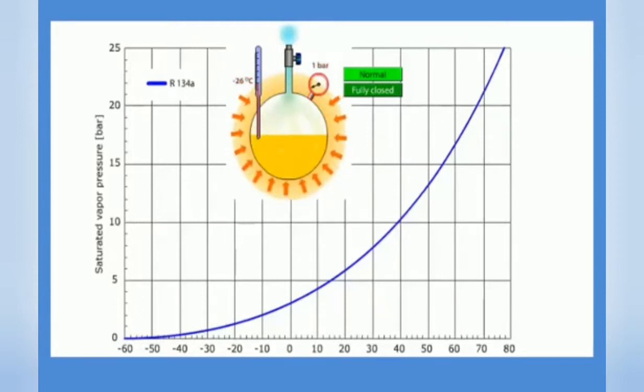When a single refrigerant is confined in the flask, it will exist in a thermal equilibrium as a mixture of liquid and vapor. The pressure in the vessel is solely depending on the temperature, which is what can be seen on the slide. You can see that the saturation pressure depends on the temperature of the mixture. The higher the temperature, the higher the saturation pressure. The saturation pressure is a unique property of the substance. The different refrigerants do not have the same saturation pressure-temperature dependency.